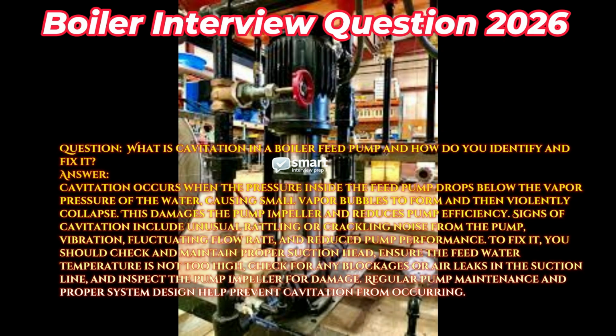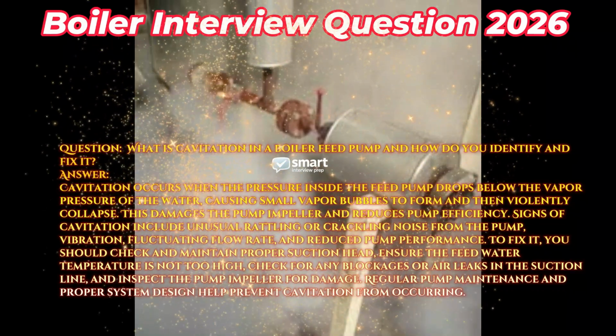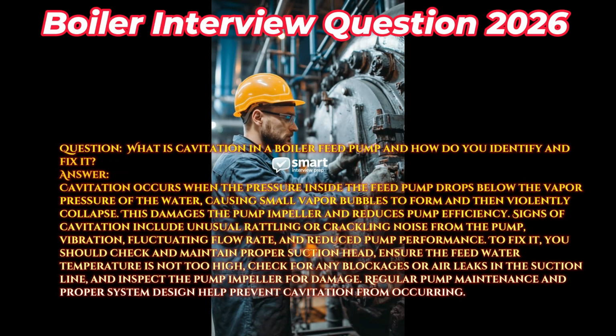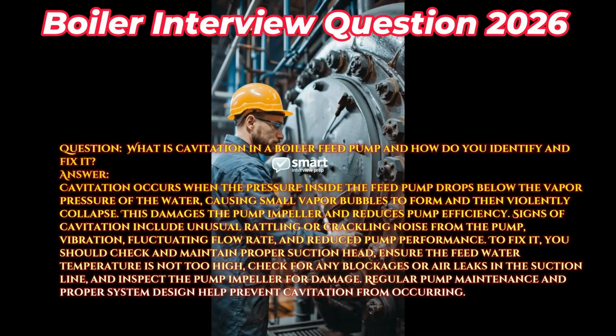Question: what is cavitation in a boiler feed pump and how do you identify and fix it? Answer: cavitation occurs when the pressure inside the feed pump drops below the vapor pressure of the water, causing small vapor bubbles to form and then violently collapse. This damages the pump impeller and reduces pump efficiency.